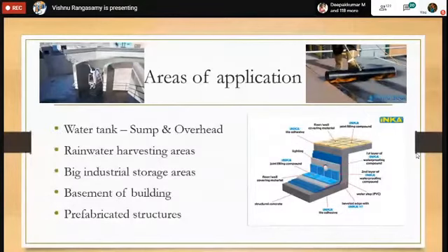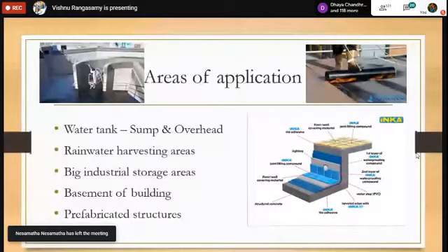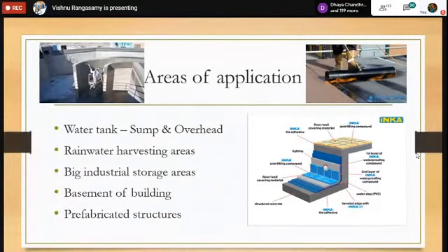So at last we found it, and it took around 2 to 3 months. We completely removed the tiles. We completely removed the mortar that was used for laying the tiles. It is a waste of time. If you are properly designing those drain pipes and going for waterproofing, then there is no need of fear in the future.